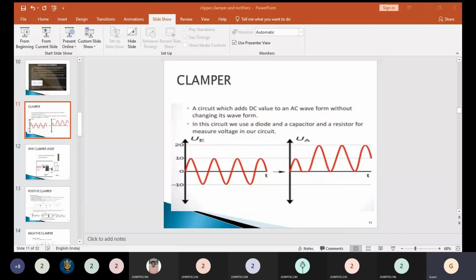First you should calculate the rectification efficiency. What is the efficiency formula for the rectifier? Efficiency is output divided by input. Input is the AC signal and output is the DC signal. So efficiency is the DC output power divided by the AC input power. Simply substitute: AC is given as 100 and DC output is 40. So 40 divided by 100 is 0.4, it is 40%. These questions will come in a GATE question paper, in part B, in 2 marks questions.